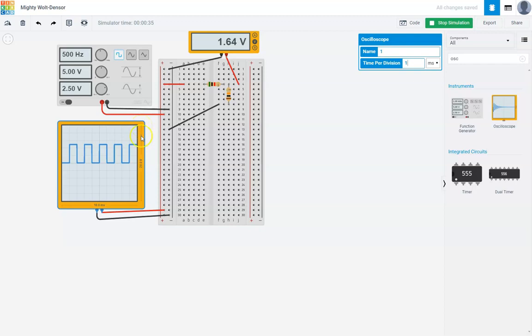It's telling me that from the top to the bottom, that's 20 volts. If you see this carefully, you see a 20 volt range on the oscilloscope. Unfortunately, in TinkerCAD, we used to be able to control the voltage division, but it looks like they've taken that option away, and I don't see that anymore. So we are stuck with what we have. I can go change this function generator to a sine wave, and I see that change to a sine wave right here.